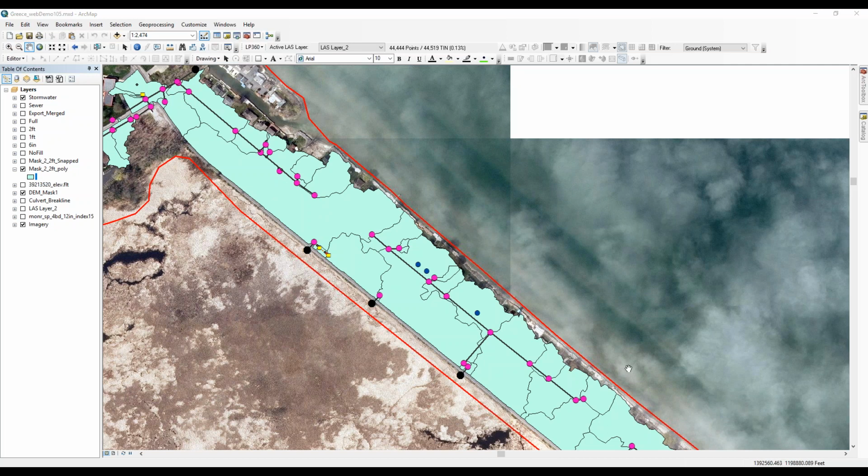So before we even go to the next step of estimating peak flows, we can use this kind of information to help us identify areas that perhaps need some additional field checking to validate the drainage and what the drainage surface is telling us, and then help prioritize what kinds of infrastructure upgrades or repairs might be necessary.